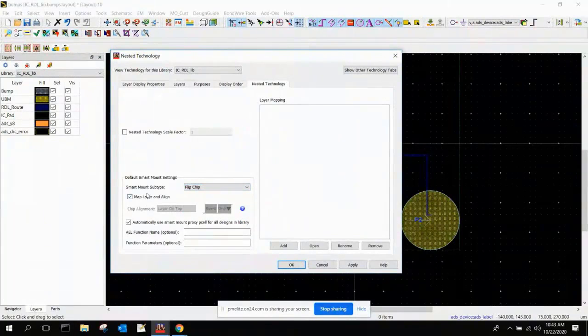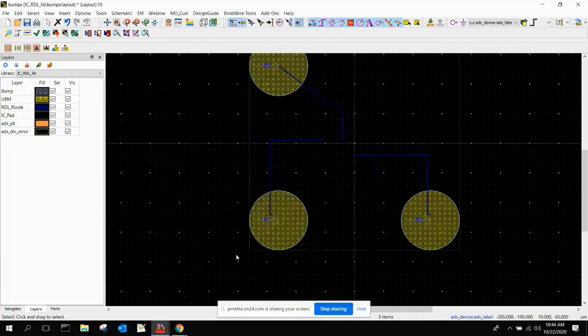And what I'm going to do is add in an AEL function. So I wrote a macro function, and believe me, if I can write a function, I'm not a coding guy, it's not that difficult. But there's a whole lot of built-in capability behind the scenes here. Also, let me make sure I got that right. Add custom landing pads to RDL. So I wrote this macro function, and this macro function is going to generate those layers on the fly.